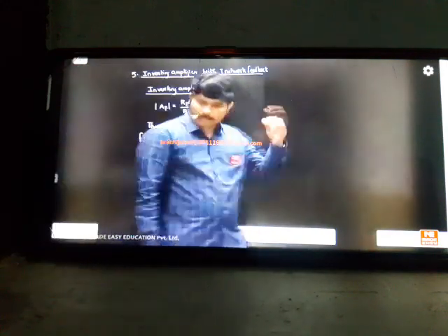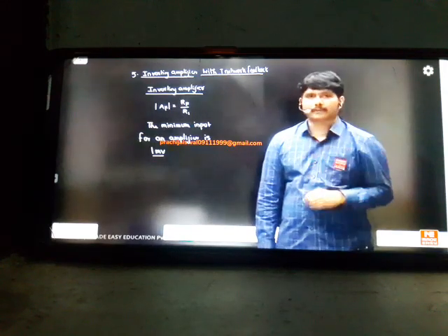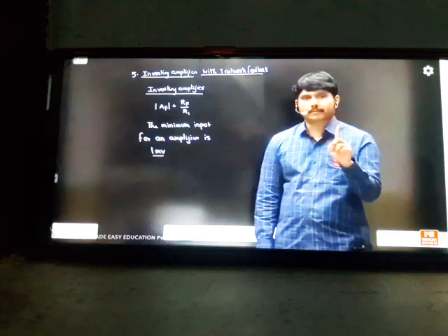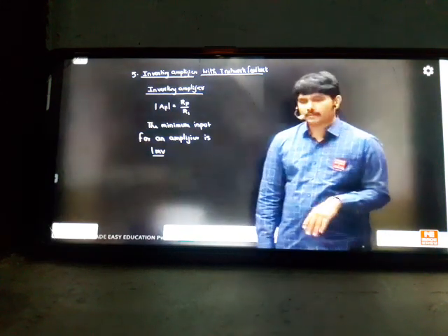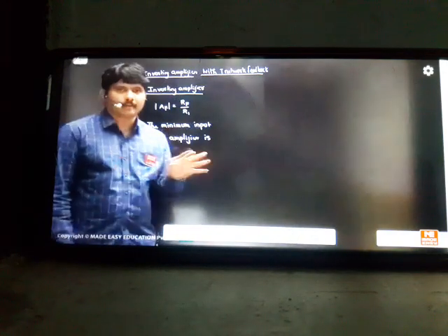So Akash Mitra is asking, is CMRR good for non-inverting or inverting? First of all, we should not talk about CMRR for inverting or non-inverting. Okay? CMRR is a term that comes from two-input amplifiers, but here we are using only one input. So CMRR is a term we should talk about only for differential amplifiers, which is my next topic. The examiner never asks you in this topic to calculate CMRR. CMRR cannot be done for single inputs. Please keep in mind, don't talk about CMRR for these two amplifiers. They cannot control CMRR designs here.